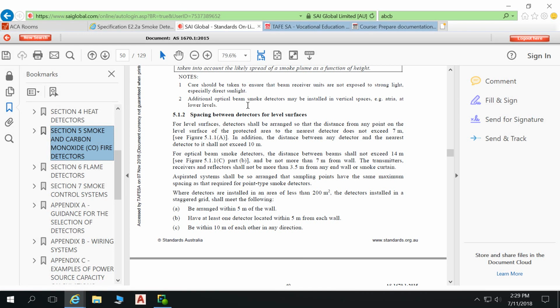But for the purposes of meeting the requirements of this unit and the subject, you've got to cover some fire safety and fire detection systems. So we can design the detector layout in accordance with this, either at a 7 meter grid or at a 14 meter grid, and that will probably allow you to not have to have smoke detectors within your kitchen areas. So you don't have to worry about specifying specific detectors for kitchen areas.